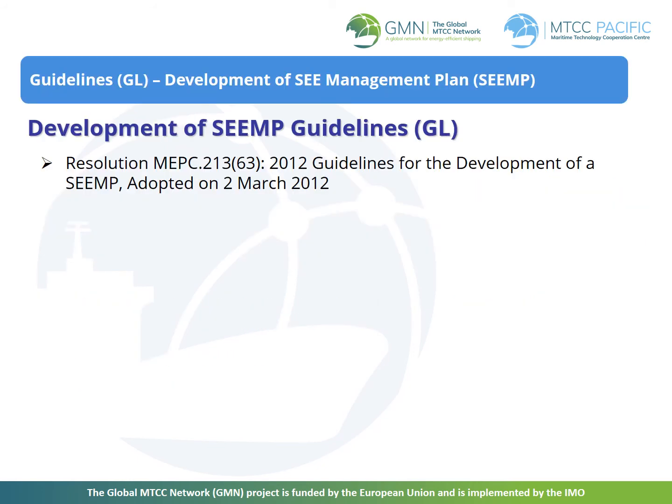According to MARPOL Annex 6 Regulation 22, it is a requirement for ships of more than 400 gross tonnage operating internationally to have a ship energy efficiency management plan on board from the 1st of January 2013. The SEEMP should be developed taking into account the IMO guidelines. Existing ships will receive an International Energy Efficiency Certificate when it is verified that there is an SEEMP on board.